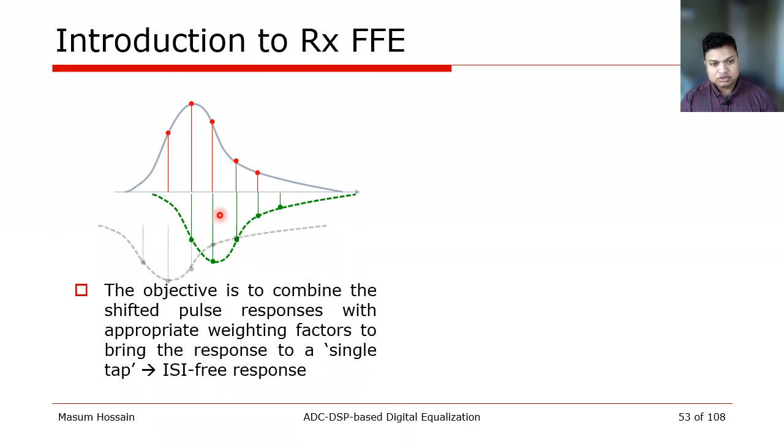A similar approach we can do for the precursor. We can shift the pulse so that the main aligns to the precursor and significantly reduces it. To keep the system causal, we would add delay to the main rather than trying to go ahead of time and cancel the precursor.